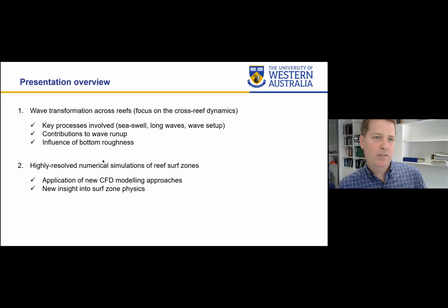So what I want to really talk about in this presentation is hone in on some of the experimental measurements we've done, looking at some of the fine details of wave transformation across reefs, focusing on the cross-shore dynamics. So I'll look at some of the aspects of how these different contributions to run-up vary on reefs, how they contribute to wave run-up and the influence of bottom roughness.